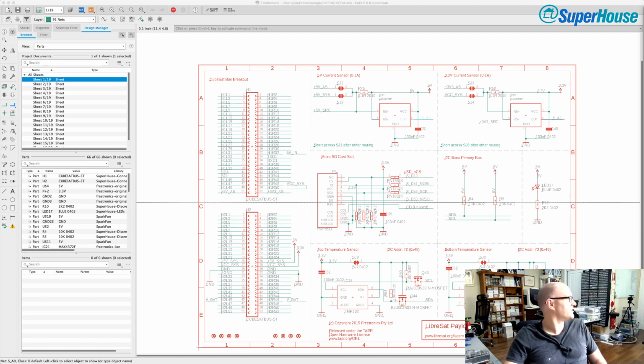I've got 1, 2, 3, 4, 5. Yeah, I've got 5 stepper motors. And most DIY pick and place machines have 6 stepper motors on them that need to be controlled independently, plus vacuum control and other things. So that's the major issue. Just think about all the things you need to control and make sure you get a board that has enough channels for it.